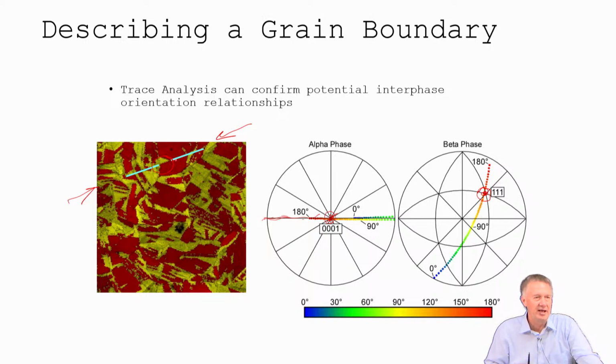Same with coherent FCC twins or coherent twin boundaries. You see the nice, long, straight twin boundaries. You know what they should be. You check and make sure it's consistent with that. And then you can go ahead and say that's where my plane is for those boundaries. Even though you can't completely confirm it experimentally, you can confirm that it's consistent with what your expectation is.